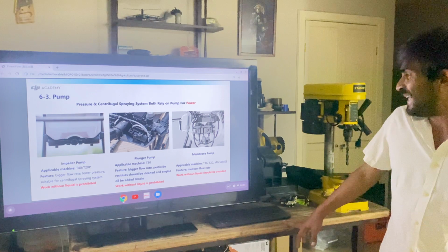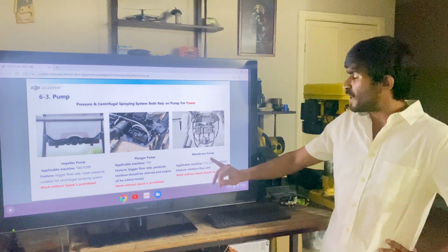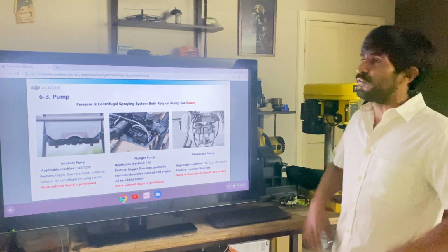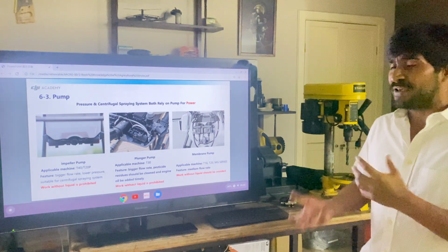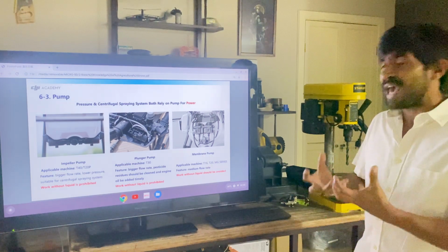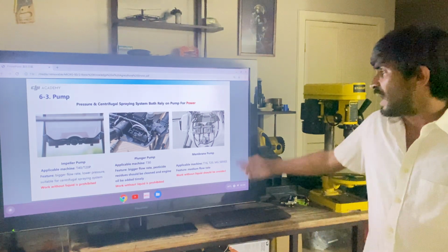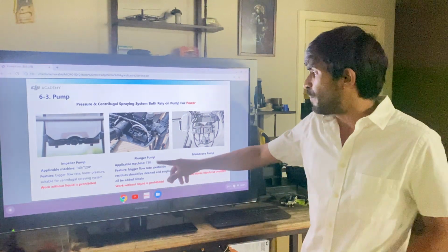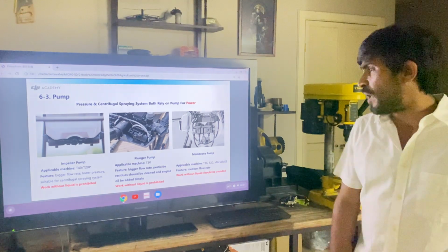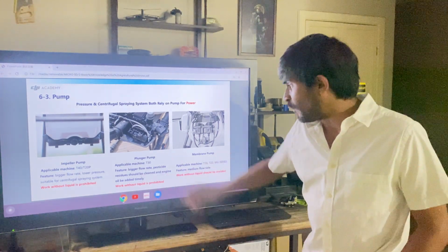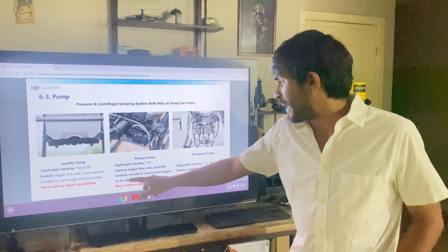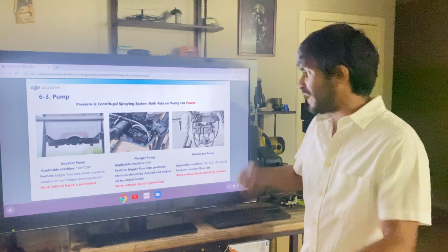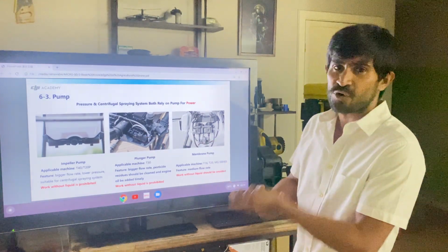All right, so what about pumps? In the T16, T20, we used to have these membrane pumps. They were good, but you have to be very careful that pesticides are not viscous, because if they were too heavy, they would jam the pumps. For the T30, DJI went to the plunger type pump, also called a piston pump, and it has a lot bigger flow rate. But it used to get corroded sometimes because the motor and the pump are in the same package.